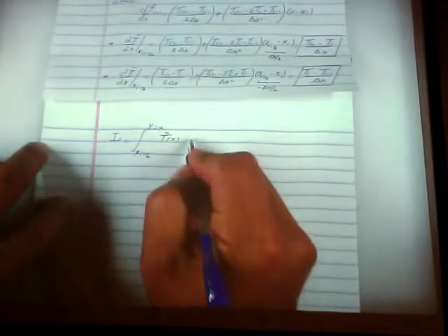So now we need integral 1 and integral 2. We need that integral of the temperature on the subdomain. So integral 1 is equal to the integral between i minus a half and i plus a half of the temperature dx.